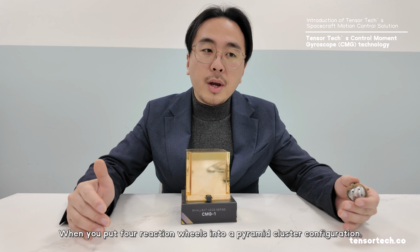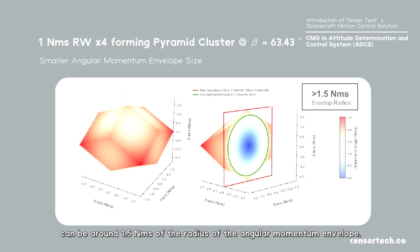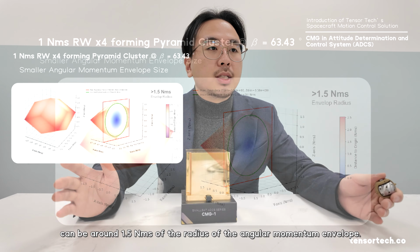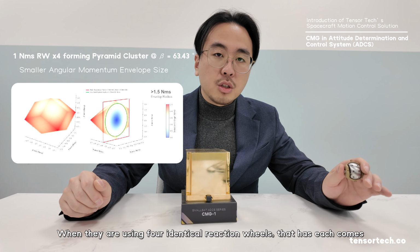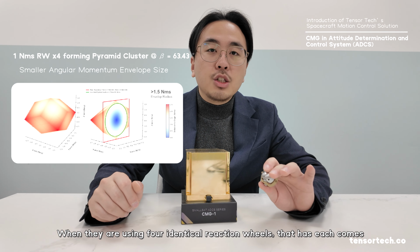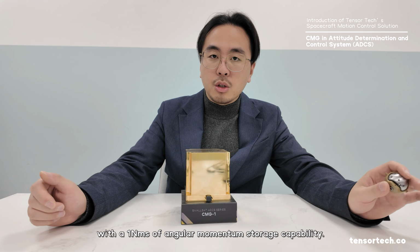When you put 4 reaction wheels into a pyramid cluster configuration, where they have the same skew angle, you can see the angular momentum envelope that it generates can be around 1.5 Newton meter second in radius, when using 4 identical reaction wheels that each come with 1 Newton meter second of angular momentum storage capability.